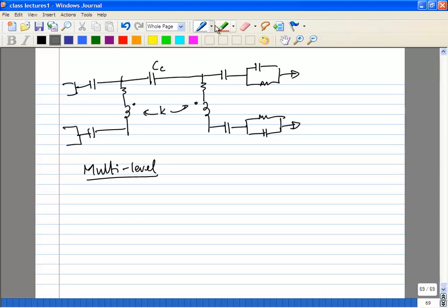There are cases where you do want that, where you don't care about the Q because it's already a very broadband circuit, or the inductor is already so de-Q'd that you're not using it as a resonant circuit, you may be using it in a different way.